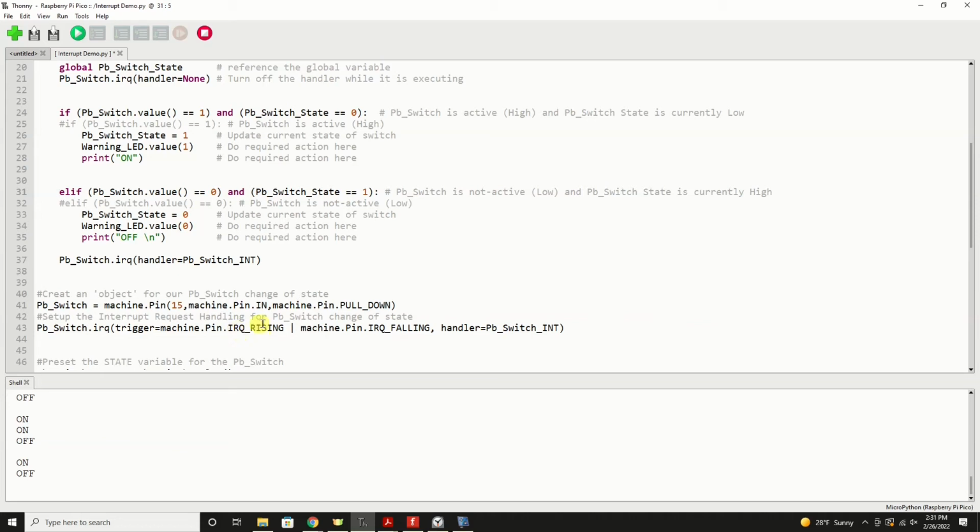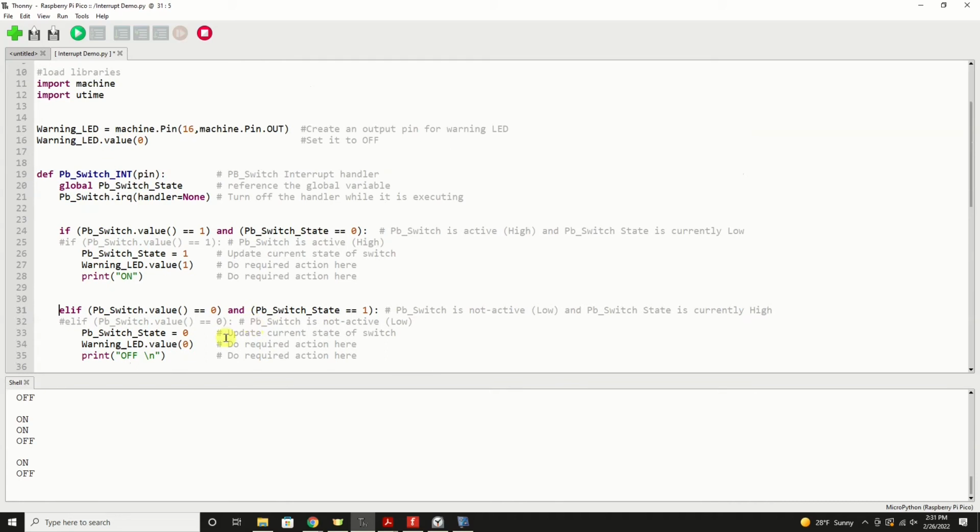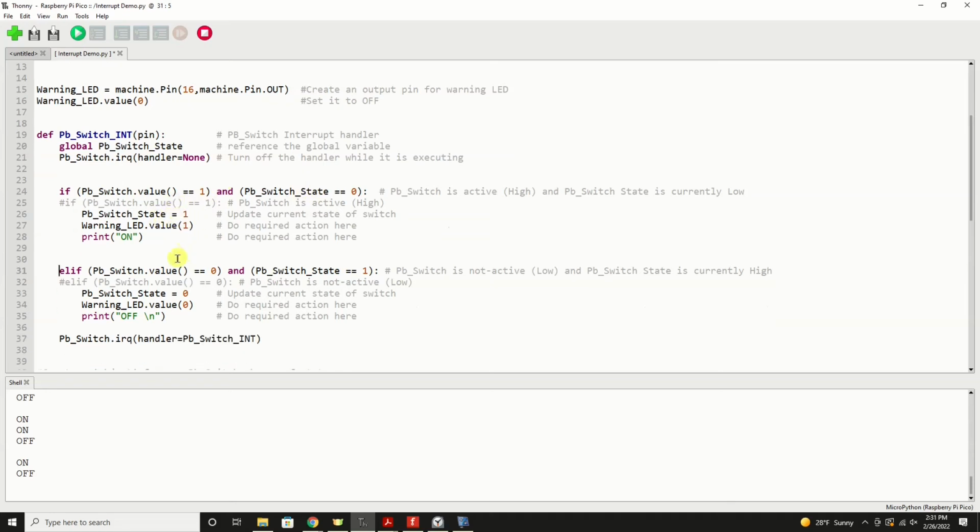If we checked on, well, it's always going to be a trigger because it's always on or it's always off. So we have a one-time, one-moment event here, and I'm comparing that moment in time against what the real switch state was prior to that moment in time. If they're not equal, then I want to execute this code.